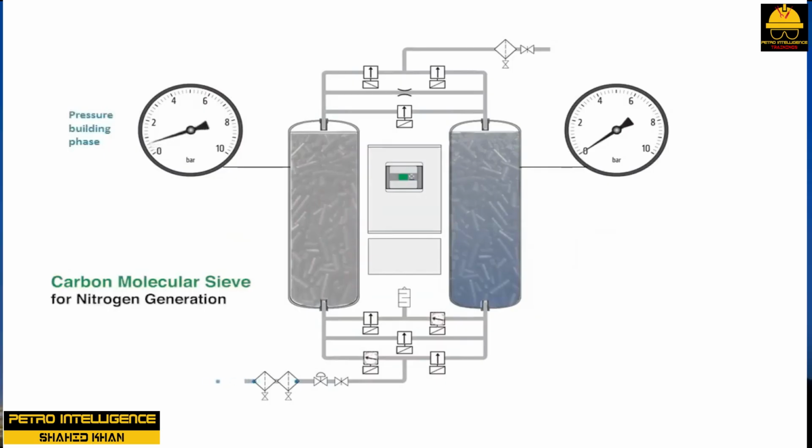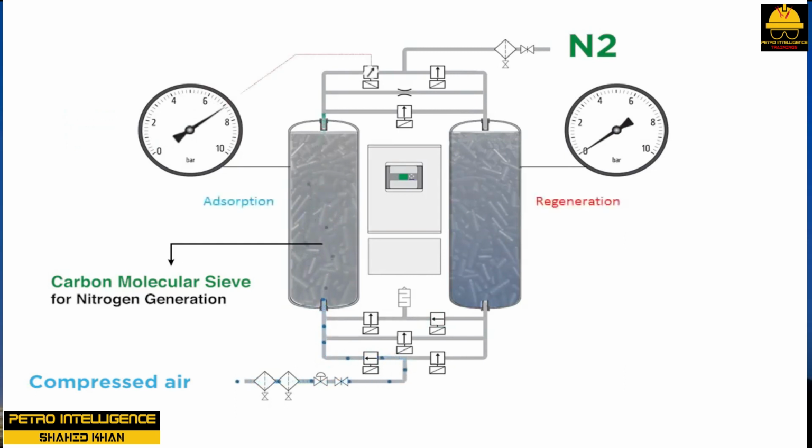Adsorption. Adsorption is the process in which an impurity is removed from a process stream by making it adhere to the surfaces of a solid. It should not be confused with absorption. During the adsorption process, a column is filled with a porous solid designed to remove gases or liquids from a mixture. Typically, the process is run in parallel with a primary and secondary vessel.